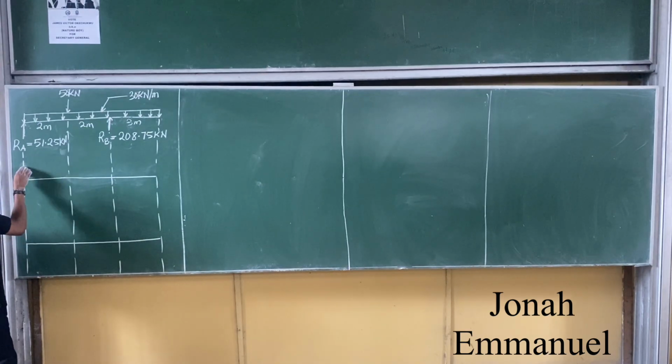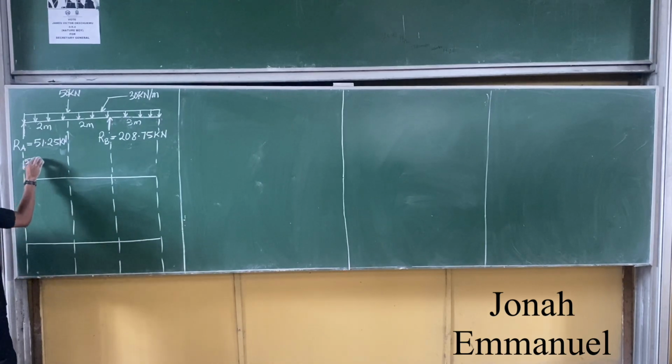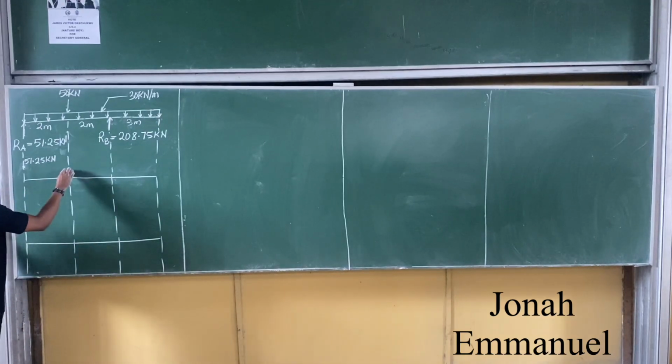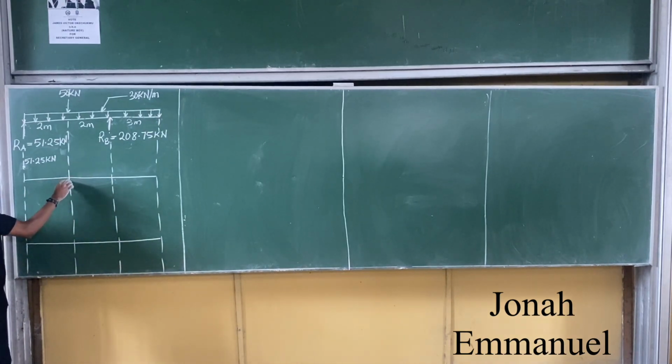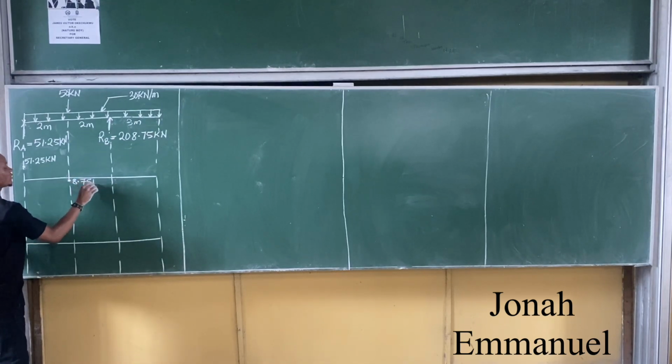I'll call here. They said at x equal to 0 here, my shear force is about 51.25 kilonewton. That's this. At x equal to 2, we had two conditions. Please check condition 1. What's the value? So look at this. Minus 8 means 8 on the negative region, I mean? Yeah. So I'll take somewhere here as being 8.75 kilonewton.